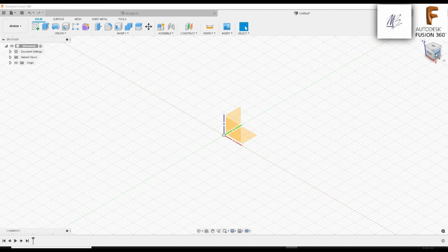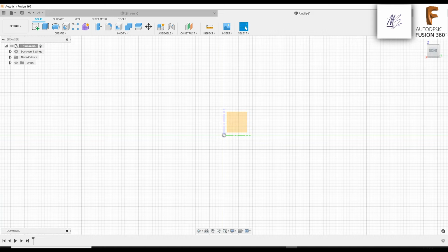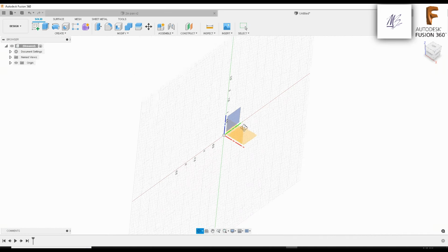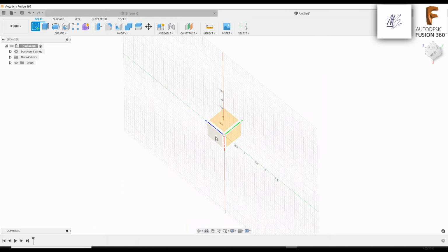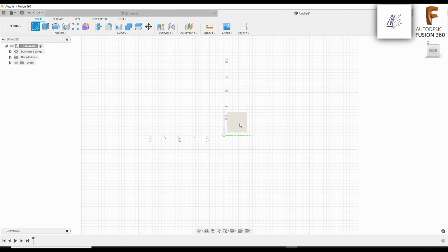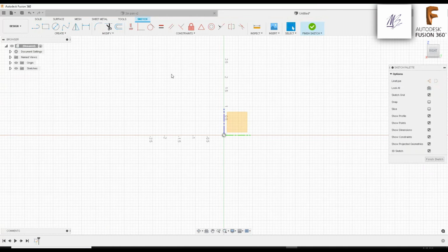We're going to do a right view, right? Because we're only going to design half of the pot and then mirror it over to the other side. So right side, you want to stay in the solid function, left click, create sketch. It's going to ask you which face. So you can choose different faces and everything you do will fall on that face. Let's stay in the right side view. Click on right side.